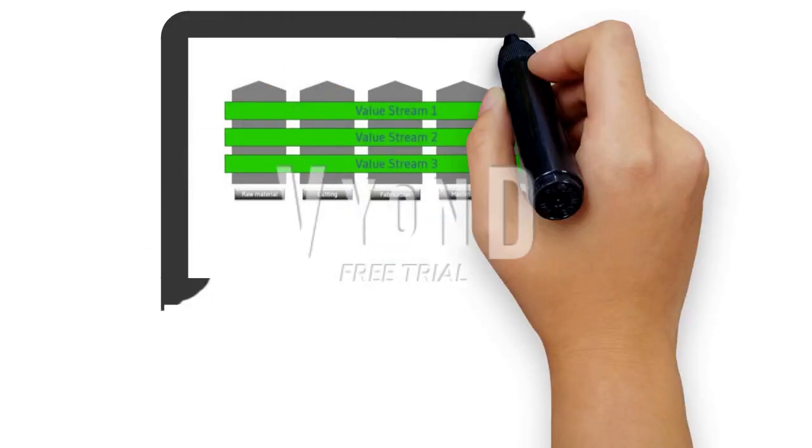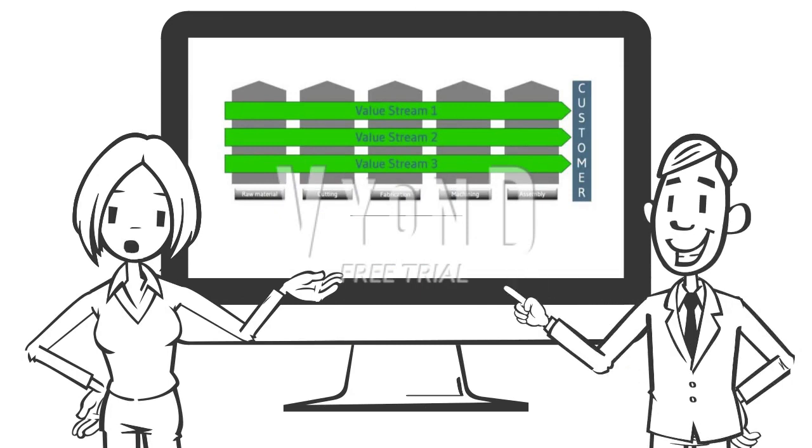Usually, there are walls between these different workshops, and materials are transported between departments by forklifts. To make production more economical, work is often done in batches, in the name of economic batch quantity. This leads to high levels of work in process inventory and long lead times. Lean plant layout focuses on value streams, all value-added steps from raw materials until the delivery to your customer.